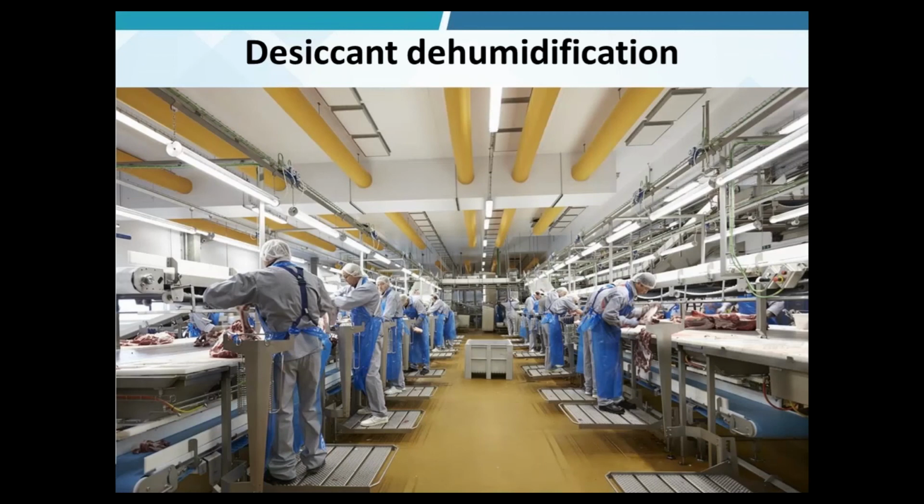One solution is to provide measurement of high accuracy for appropriate, precise control as required to ensure air quality of the in-process material or the controlled environment air. For example, in desiccant dehumidifiers, also called moisture absorbers. Also, with increasing automation connectivity, it may demand for the sensing device a communication interface beyond the normal analog retransmission outputs.